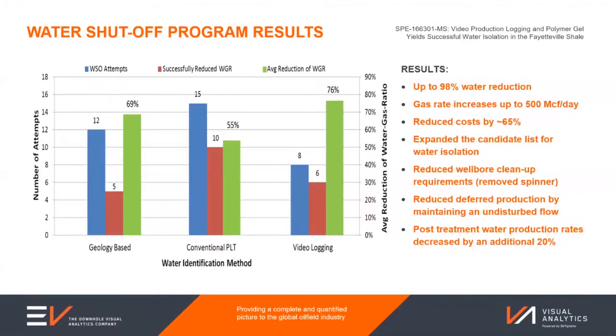And compared to the conventional technique of squeezing cement into these zones and then milling it out, the cost of using the polymer gel was so much lower that they were able to add an extra 25% of remedial services for the same overall budget. They were also able to reduce the cost of the diagnostic services by approximately 2/3. And that's because we're now using slim, simple centerline tools that would fit through the existing completion and work with great effect. So those two elements in combination gave a fit-for-purpose solution. It had great results and at a lower cost point than the conventional techniques.